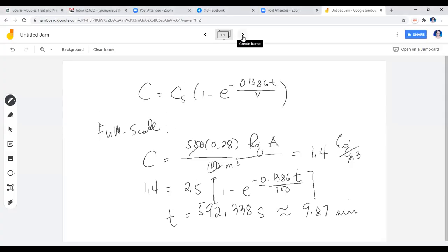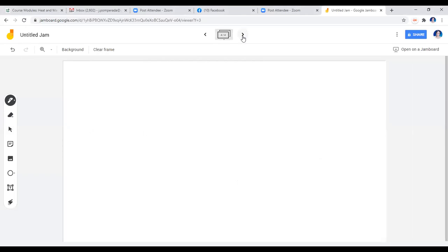Okay, so from time to time I will go back to the slide to get the information that we have. In sample problem number 2, these are our given information. We'll read the problem one statement at a time. Statement number 1: in a single-stage leaching of soybean oil from flaked soybeans, so we take the oil from flaked soybeans, we use hexane, and 100 kilograms of soybeans containing 20 weight percent oil is leached with 100 kilograms of fresh hexane solvent. So how would we write this down? 100, 100, and 20% oil in this case.